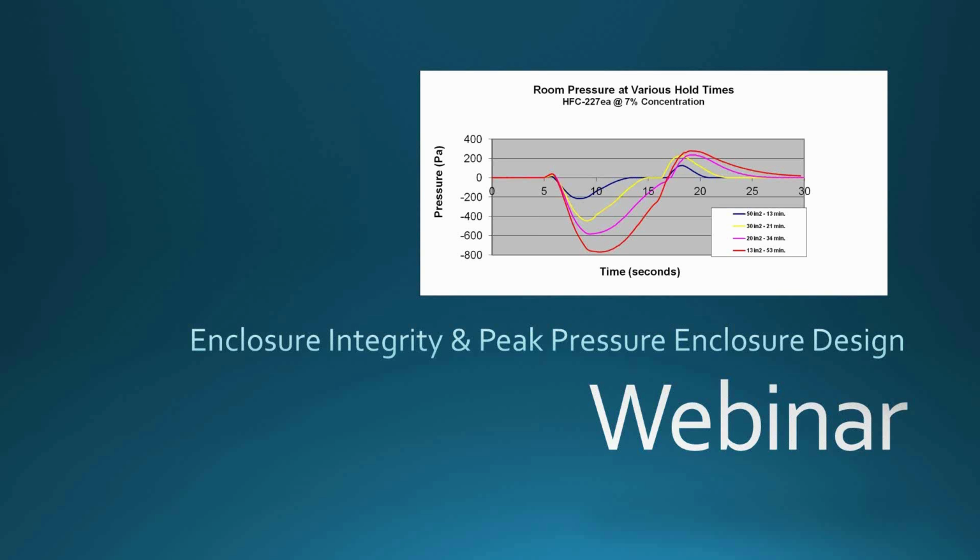The first slide I'll address essentially talks about the discharge test. Before 1988 all systems were discharge tested, and it turned out it was costly, time-consuming, and disruptive. Before that, in 1984, I proposed using door fans and an algorithm to test enclosures, because mostly they failed because they were too leaky. And of course, since then we've had NFPA 2001 and a lot of things.